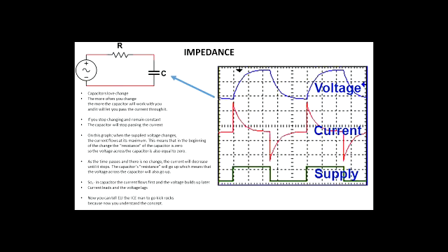So what do we have here? On the bottom here, we have the supply voltage, and I put a square wave just so we don't have any gradual transition. So basically, all of a sudden we apply the voltage, carry it on, and we go to zero, and so on. So what's happening in the RC circuit here? This is the current, the red one here. The red graph is representing the current over the whole circuit.